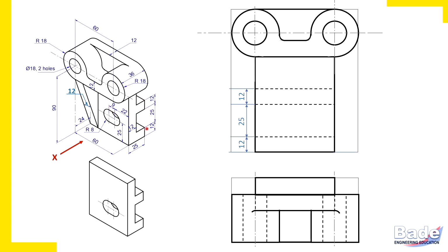Except for the hole, this whole front view of the object is complete here. Now in the top view, same 3 edges. So these edges we are drawing here in the top view will overlap with already drawn edges. And that is why these 3 edges or the edges from these corners will not appear in the top view. Not appear in the sense they are already overlapped in the earlier drawn edges.